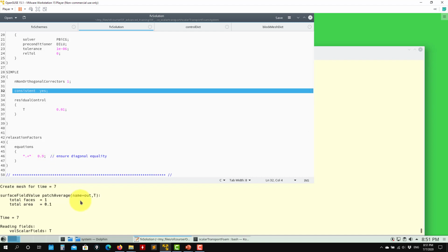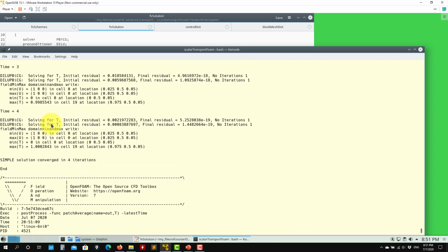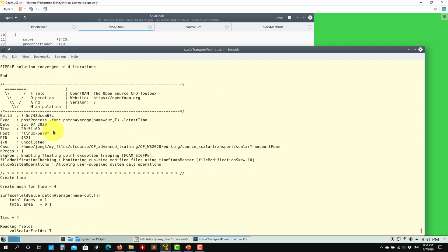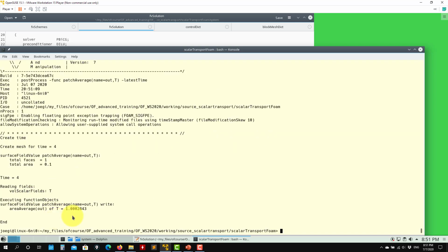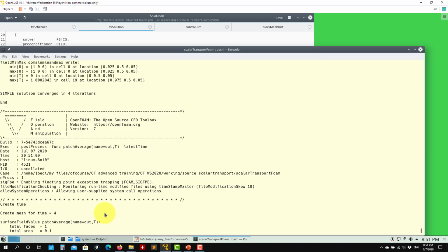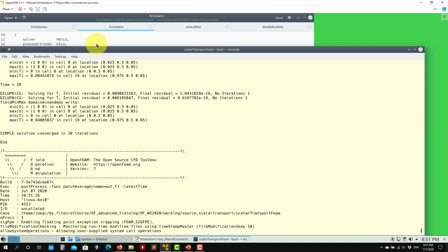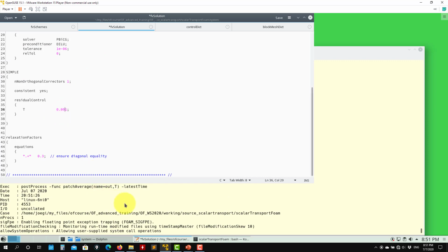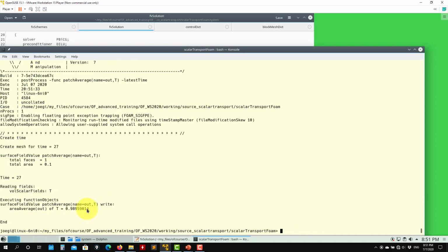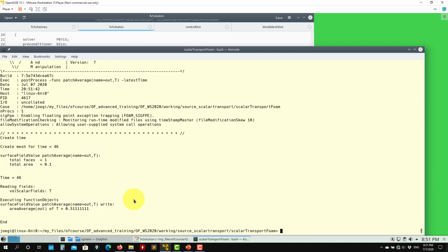So we have the gradient limiter, the new thing that we added, and see that by adding the gradient limiter we have a much better behavior. In 4 iterations it's convergent, and we don't have those strange oscillations anymore. Let me reduce here to 0.3. Now the problems will be with the tolerance here. If you increase this one, you might get to the value. So here you put 0.1. Here we're going to the starting case. This is our starting case.